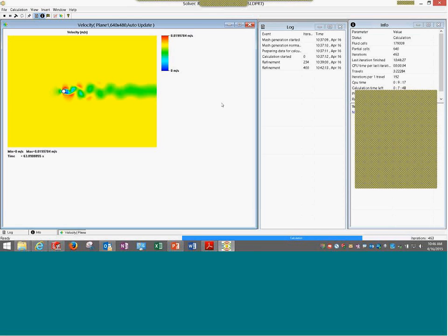I'm using this kind of turbulence with adaptive meshing. There are also some options in the mesh controls which allow us to tell the software to create more elements near the boundary layers, which helps make sure the boundary layer is captured properly.